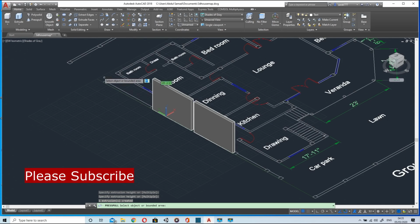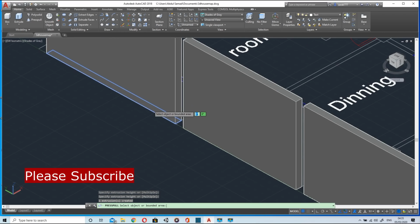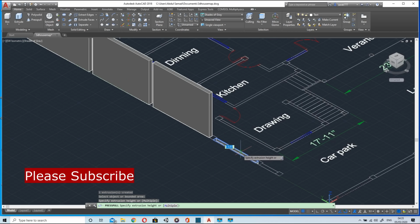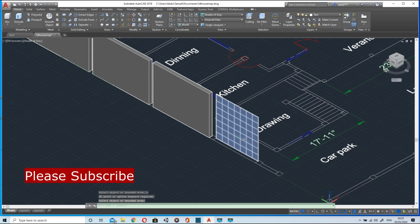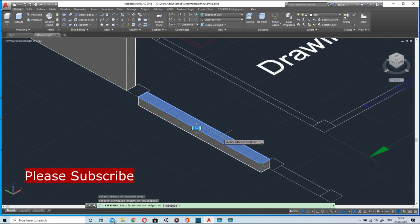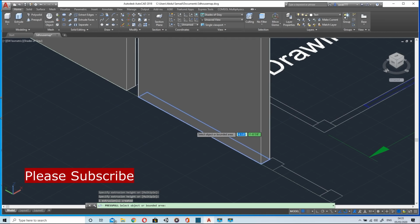You have to place the square box inside that area that you want to extrude. Once you add the extrude distance, you can extrude the rest of the rectangular surfaces by just clicking in that area and pressing spacebar.